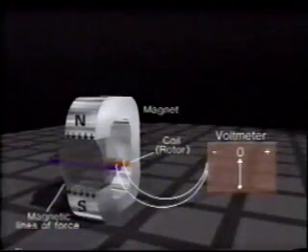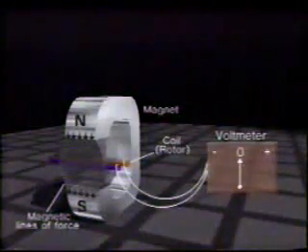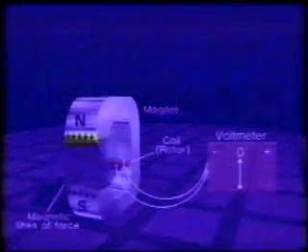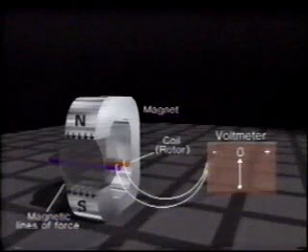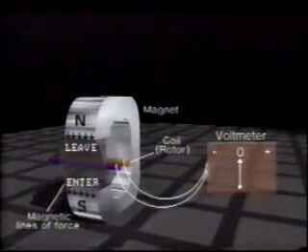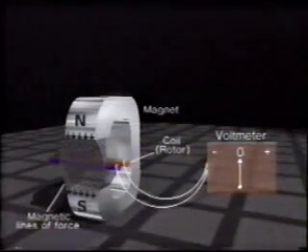This simple AC generator consists of a coil or rotor rotating in a magnetic field. The magnet has north and south poles and its magnetic flux passes through the rotor. By convention, the lines of force or flux leave from the North Pole, pass through the rotor, and then return to the South Pole. So the lines of force at the South Pole are set up in the opposite direction to those at the North Pole.